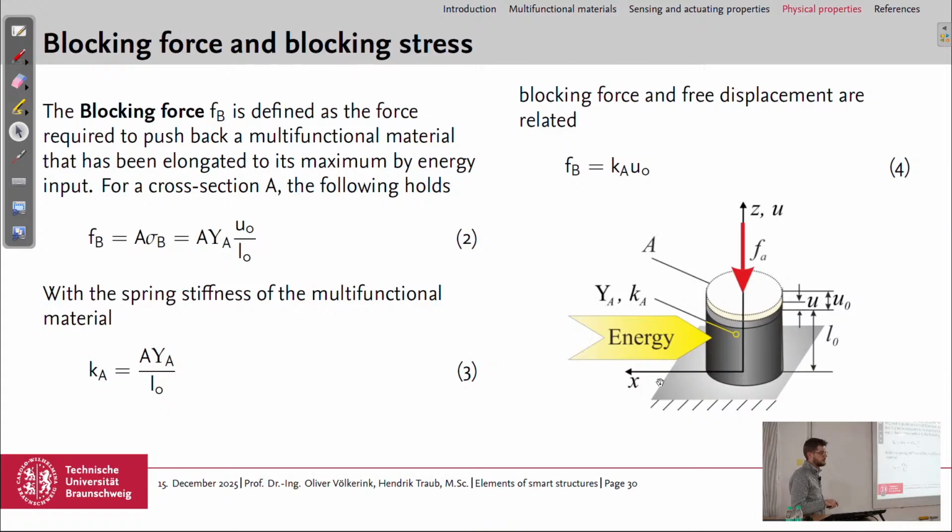So from the idea, if you just have a block of the piezoelectric material and maybe some electrodes to apply the electric field, then in the first step, you will measure the free displacement, just applying a maximum electric field and see how it extends, and measure this U0. And then in the next step, you would push it back to U0 while maintaining the electrical field. And this is then the blocking force. This is the maximum force you can apply with the actuator without any movement. And you will also do this in the first lab experiment on your own.